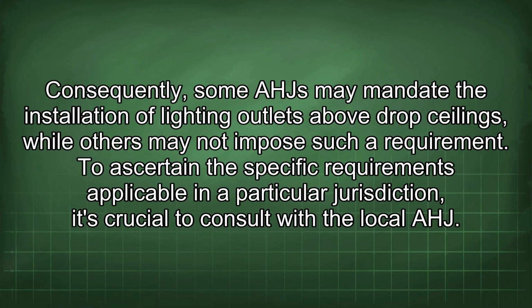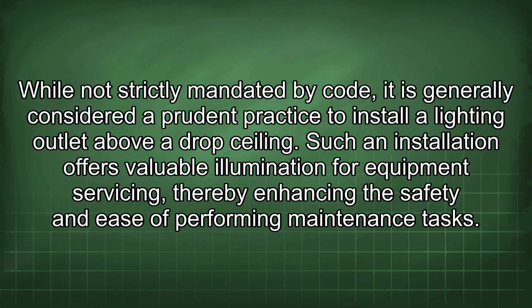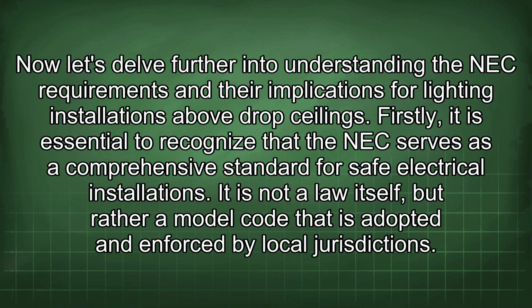local AHJ. While not strictly mandated by code, it is generally considered a prudent practice to install a lighting outlet above a drop ceiling. Such an installation offers valuable illumination for equipment servicing, thereby enhancing the safety and ease of performing maintenance tasks. Now let's delve further into understanding the NEC requirements and their implications for lighting installations above drop